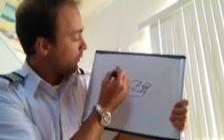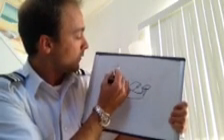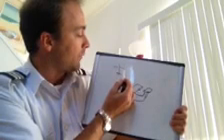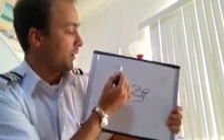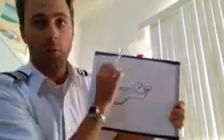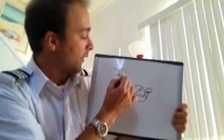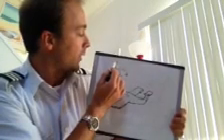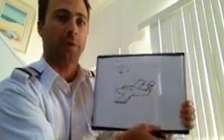Let's see how we do it. We'll draw a top-down view. So this airplane's going left. This aileron has been dropped into the wind, creating more lift and more induced drag, which is going to cause a yawing moment back this way. But we're wanting our aircraft to go this way. So it's not going to cancel it out, but it's going to cause the nose to go slightly in the opposite direction of our desired turn.